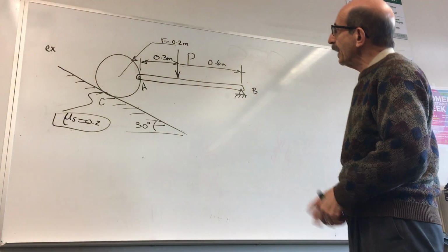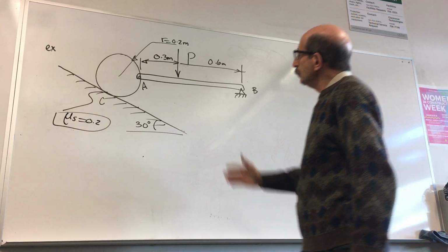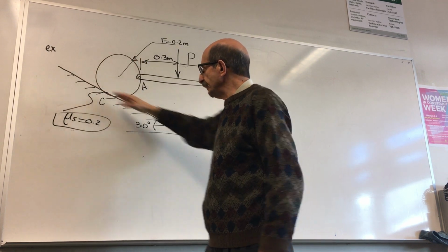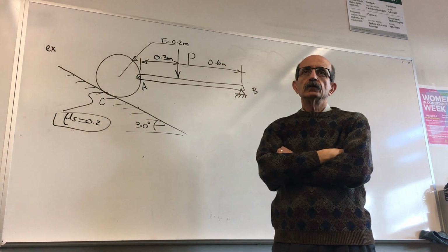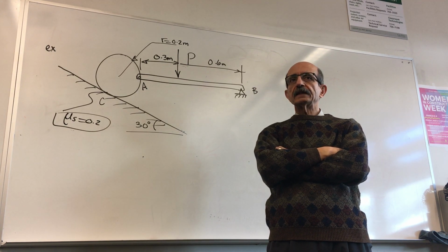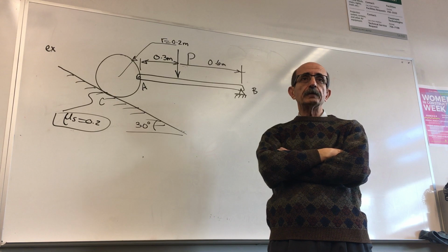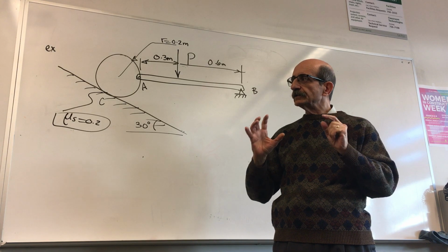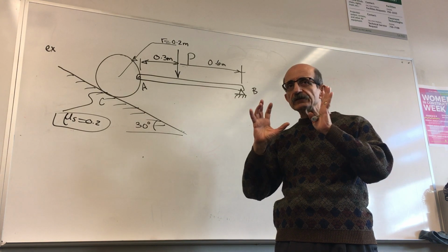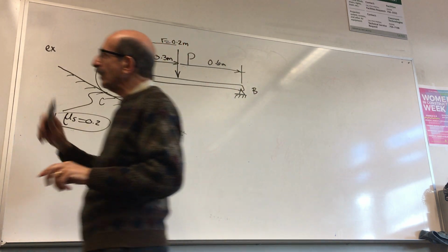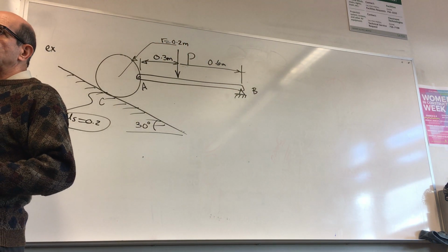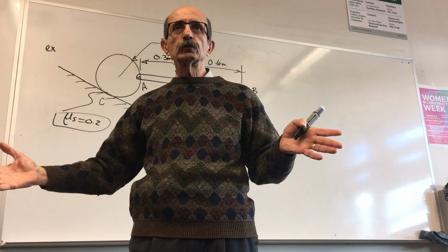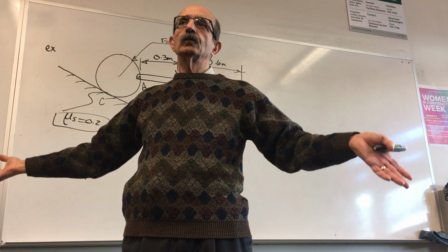As the problem states, in other words, how large this force can be so that this disk still does not slip along this surface. So the maximum force P that yet doesn't cause a slippage of the disk along the surface. In friction problems, the first and most important thing is to read the problem statement, and as step one, identify whether you have case 1 or 2. The minute you hear that no slippage or motion is going to take place, that means it's case 1, right?